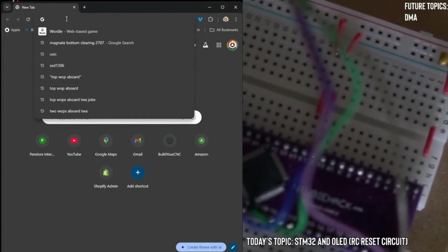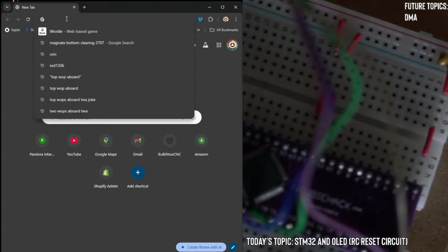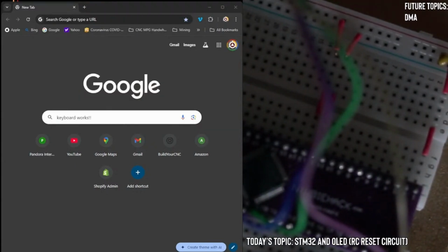I'm not going to put a button on the reset unless I need to add a reset just to reset the microcontroller and make it so that part works right. But what am I trying to think? The process of flashing the microcontroller, I'm thinking, does some kind of reset to the microcontroller right before it does the flash. So that's where I'm thinking what he was talking about.